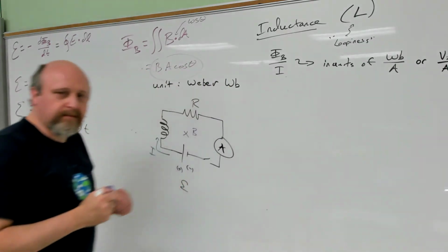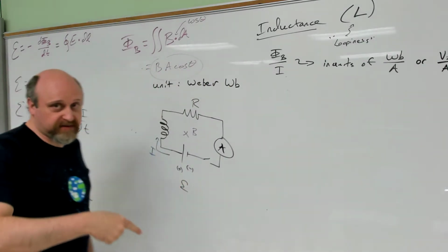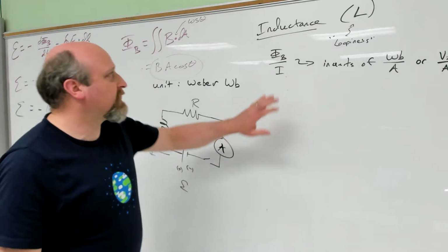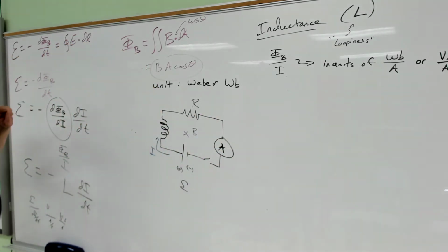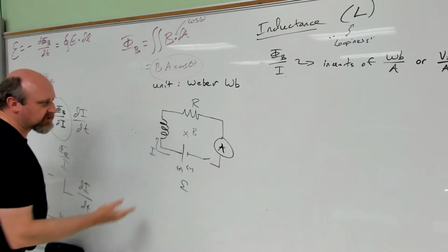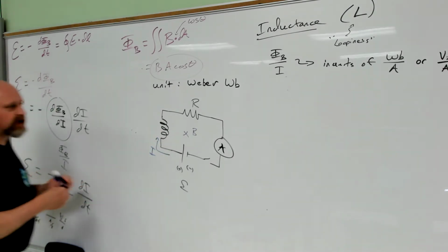Now, there's one more thing I want to show you about inductance, before we start talking about what it actually does in the circuit. One more thing about inductance, and that is, we can calculate it. This is really just the ratio of how many field lines we get going through our loop for every amp of current that we run through it, through that circuit, or through that device. That's our L value. I'm going to label that right on the diagram.